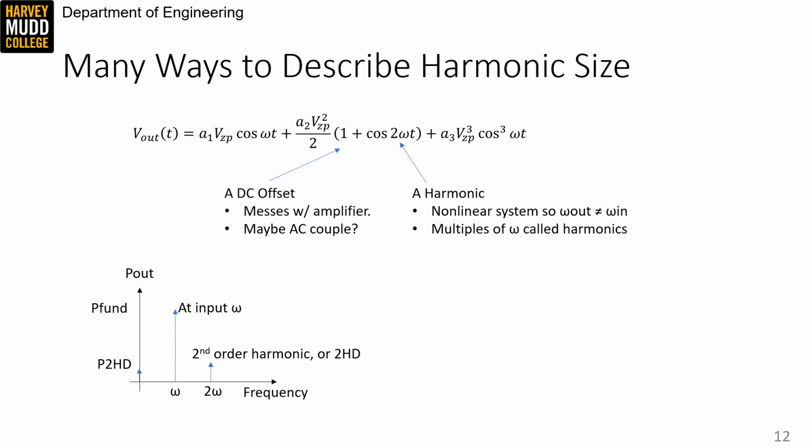This graph is a great summary of what's going on, but we can come up with some concise numerical summaries too. First, it's common to describe the power of the second harmonic in relation to the power of the fundamental signal. We do that by using yet another funny decibel unit called dBc, or decibels relative to the carrier. We'll talk about where the term carrier comes from in a later video, but for now just remember that it refers to the fundamental.